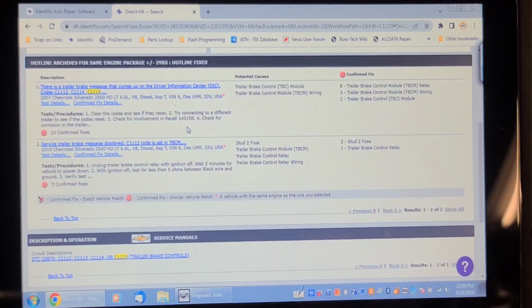I've tried a new trailer brake control relay. The one that's in there was replaced as well. I've tried to load test the wiring from the relay to the trailer brake control module. I've confirmed power and ground. I did fix one power wire at the feed stud, but that didn't fix it. I've load tested the wires with a headlight, so that should qualify them.